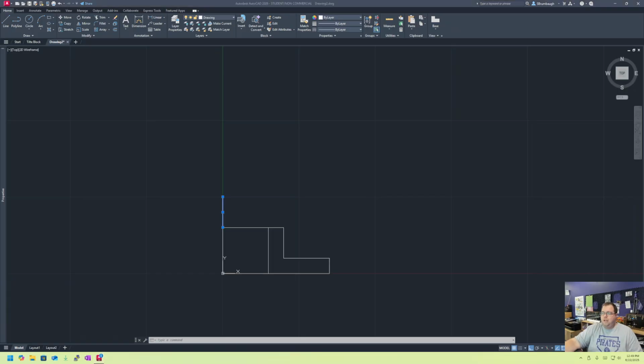So if we look at our drawing, which you should have open in front of you, that point is kind of in mid-air when it comes to the top view. So I'm going to start another line. I'm going to connect it to the beginning of the line we just created. And I'm going to come up another inch because that's how far it is on the top view.